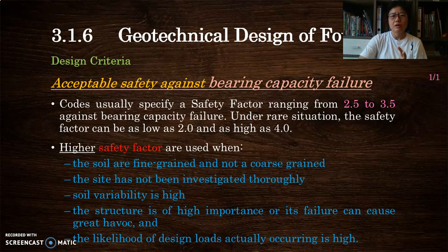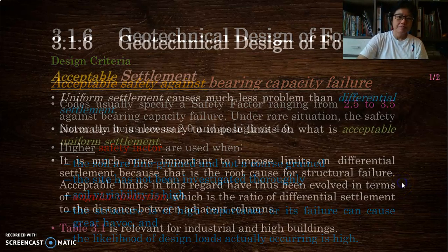You are not sure, wherever you put in your foundation, whether it's going to be safe or not. And the structure is of high importance, and you cannot allow any slight failure. Like KLCC, you cannot allow it to start tilting and things like that. So these kinds of structural safety factors will be very high for the foundation design, and the possibility of design loads actually occurring higher than what you expect. So that is another situation where you have high safety factors.